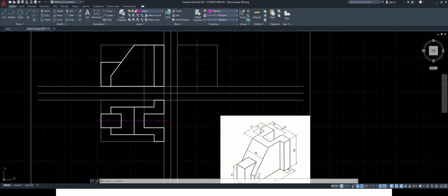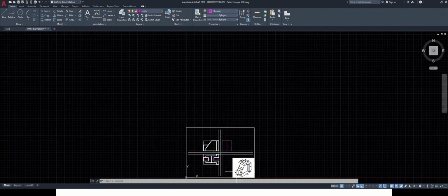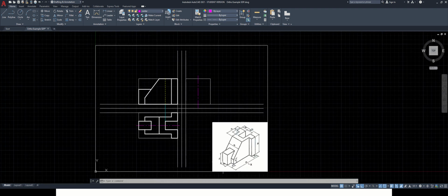So first thing that is visible to us is this box, which is of size how much? 20 by 35. So switch on the layer of object line, line command. From here we have to go how much? 10, enter. Height you can take it or trace from here, 35, then 20, enter. Downside and close. Press escape.